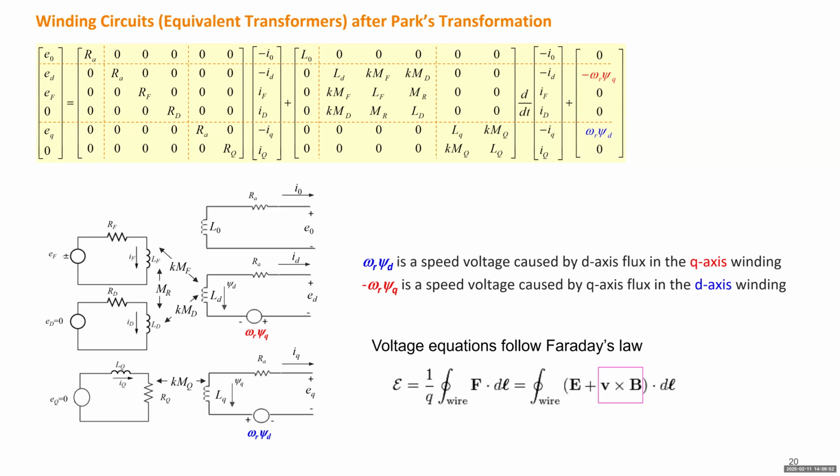So what is the source of the generator now? Basically this one, right? That's the only source. And those 2 are 0, right? So you are using the field winding as a source to input some electricity, and at the terminal you will receive some electricity. That one can be ignored because the field winding is not the major source of the generator. It only generates the magnetic field. So the real electric source is caused by the revolution of the rotor. You have to make this speed high enough to induce the electric field due to this one.